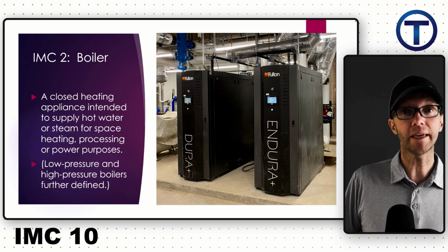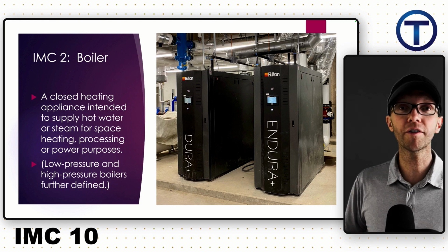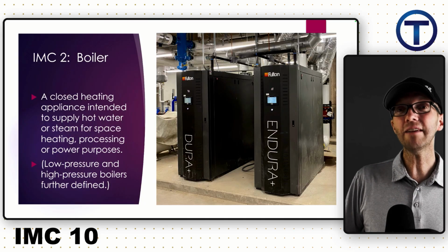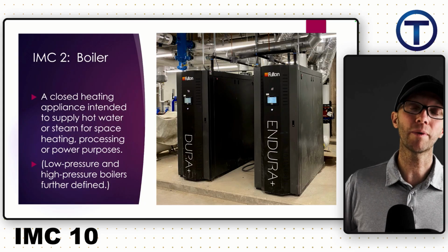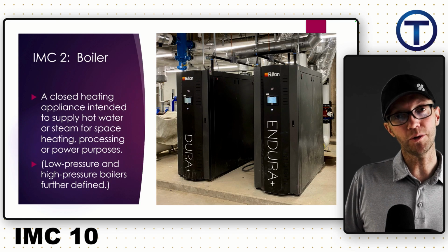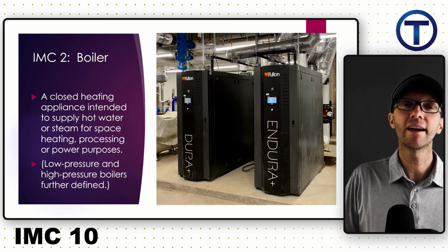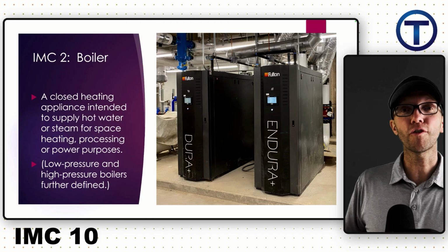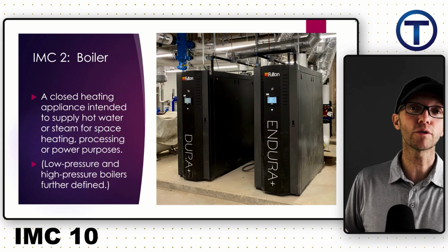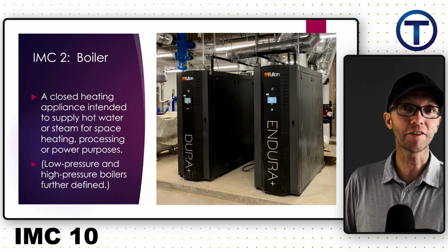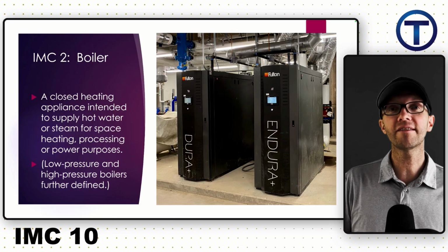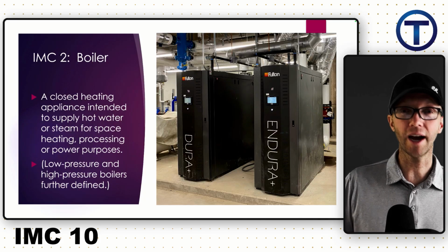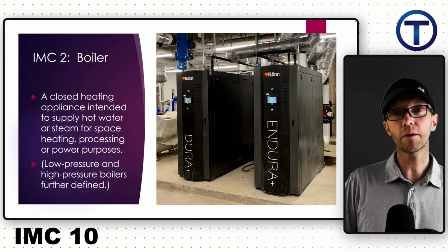Now, can boilers be used to heat potable water? Yes, they can. We can have heat exchangers, or they can even be an open system that pass water right through. Please don't get confused here. We're generalizing. Water heaters are for potable, open systems, and boilers are for closed systems that are used for heating space, generally, right? There are also in this definition some more specifics about the difference between low pressure and high pressure boilers, but let's just stick with the basics.